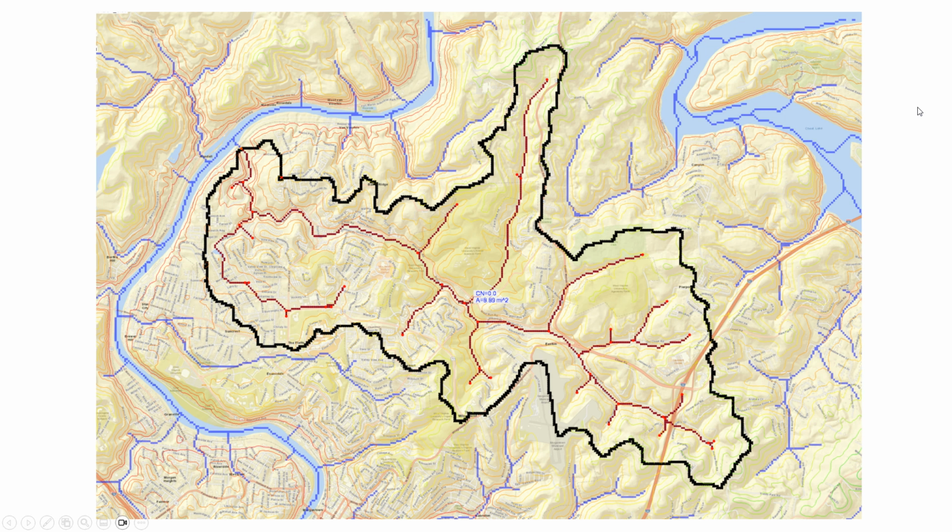I'd like you to calculate the curve number. In the handout I've just given you, you can see there's some blanks that you need to fill in, like what's the curve number based on the land cover and the soil type, and what's the 10-year runoff peak flow rate based on HEC-1. So I'm going to delineate the watershed. I'm not going to narrate through my steps. I'm going to delineate the watershed and calculate the curve number, and then you do the same, and then we'll see if we get agreement on the area and curve numbers, and then we'll go through the subdividing process together.